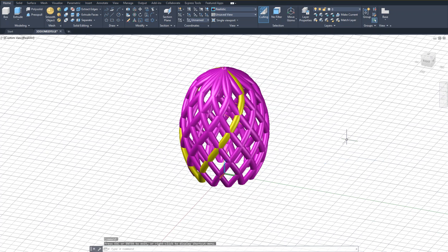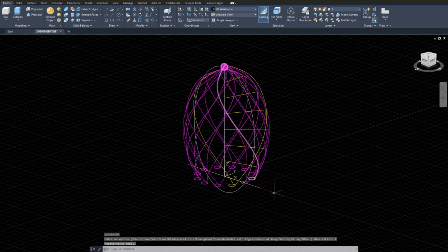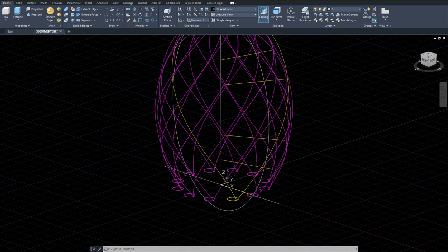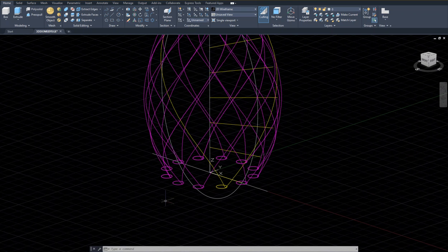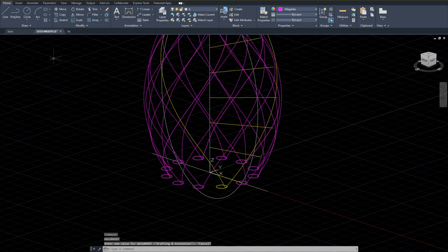All right. So I'm going to just switch back to Z, enter, previous, enter, and I'm going to shade mode to complete the design, enter, and wireframe. So we need to go to the two-dimensional wireframe option. Okay, these are all good. So why don't we draw a circle first and then make some extrusions over here, okay? So I can go with the circle command, but I want to change this back to two-dimensional options, all right? And select the circle and pick the 0,0 point.